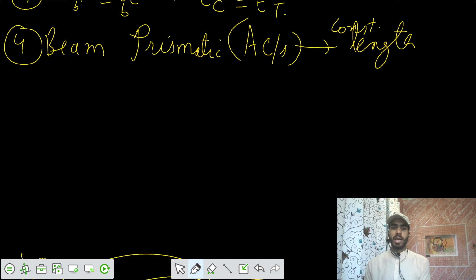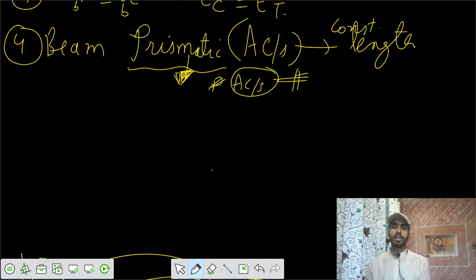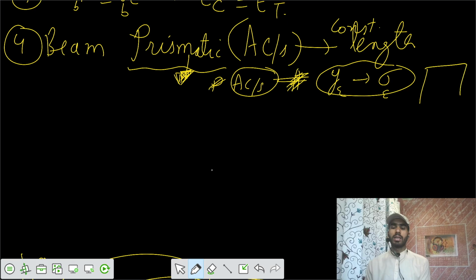We don't want to have this as a variable. For the derivation, we don't want the area also to be variable. In further studies, we can vary the cross section also. But for now, let's keep it as a fixed parameter to study the influence of strain and stress. We want to see the effect of the strain and stress only because of a bending moment that is constant.